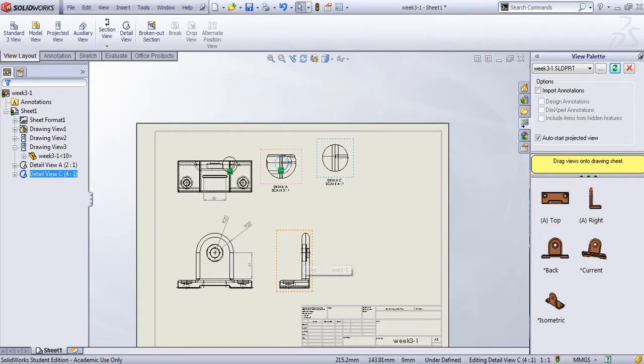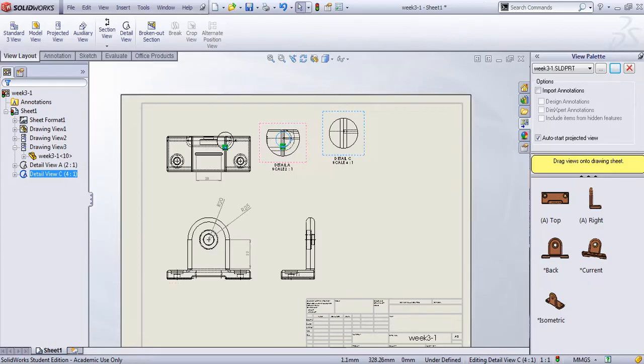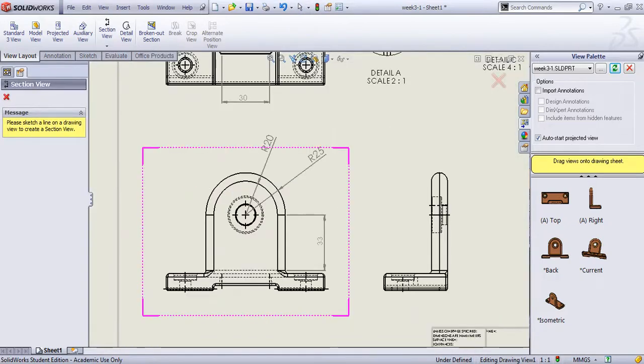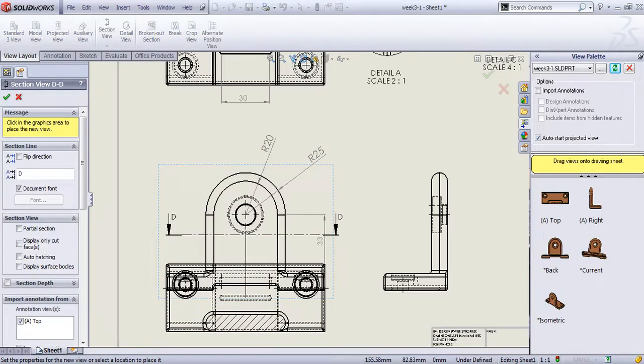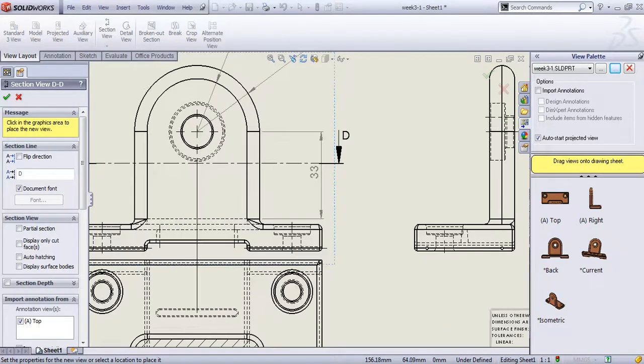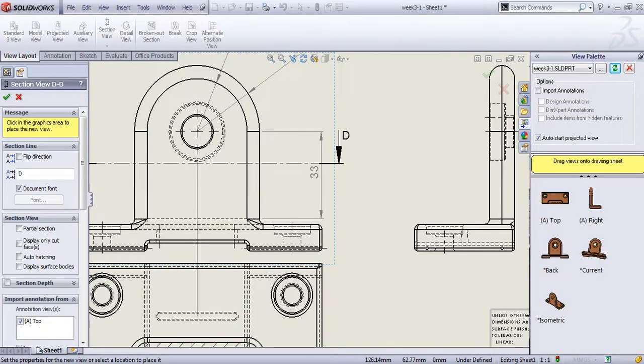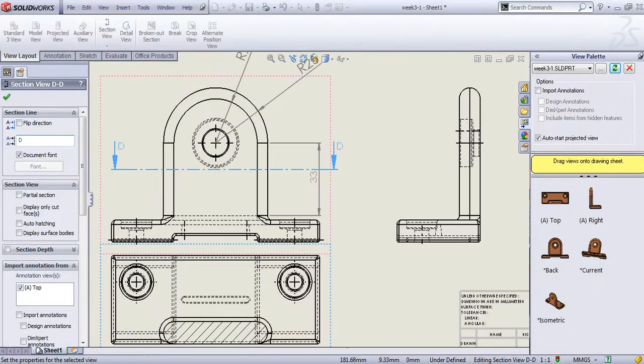Sectioning is also very important. For doing sectioning, we're using this option here. I show both of them. Let's do a straight sectioning. In that case, you want to, for example, section this part. You go from here, section directly up to here, and look at that now. When you section that, this is what you get. So let me just place it here.